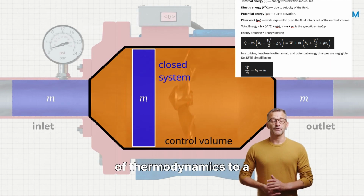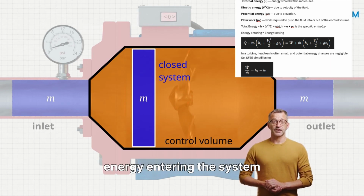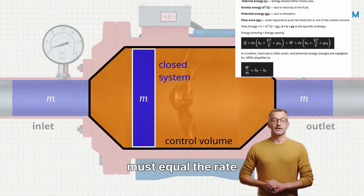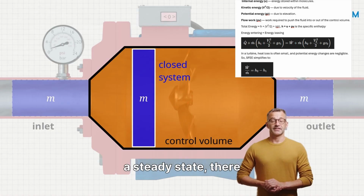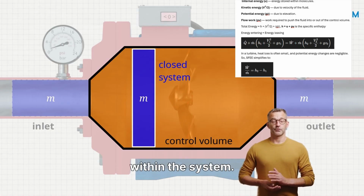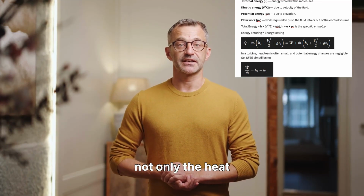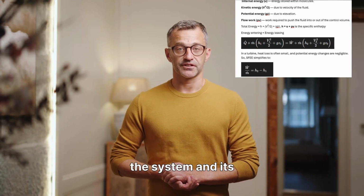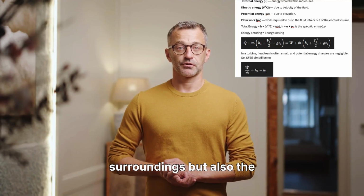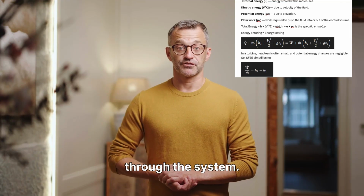Applying the first law of thermodynamics to a steady flow system, we state that the rate of energy entering the system must equal the rate of energy leaving it. This is because, in a steady state, there is no accumulation or depletion of energy stored within the system. This energy balance includes not only the heat and work interactions between the system and its surroundings, but also the various forms of energy carried by the fluid itself as it flows through the system.